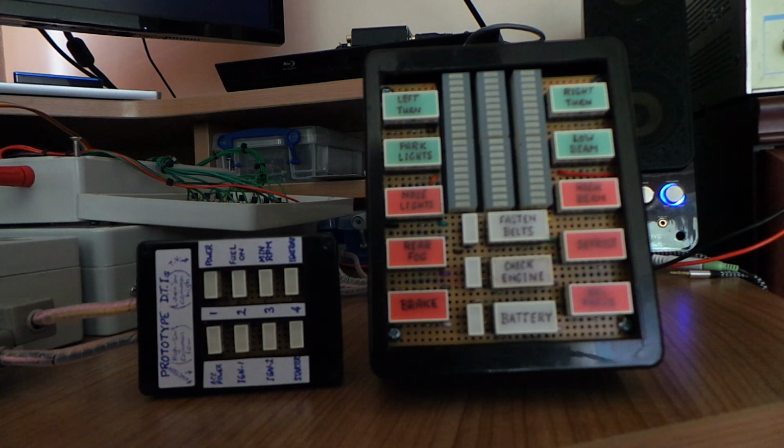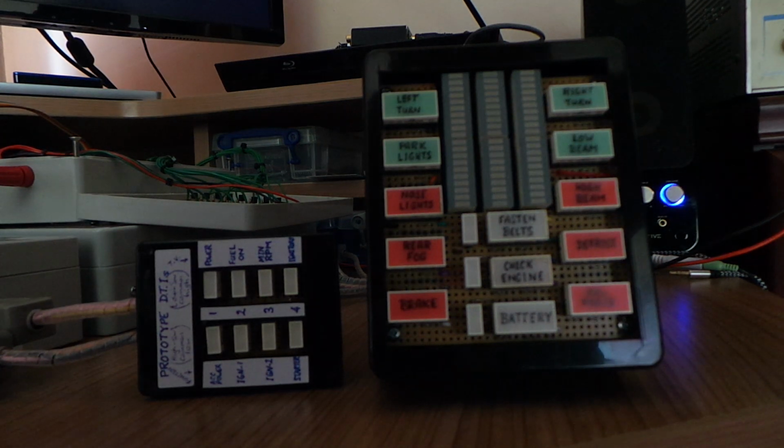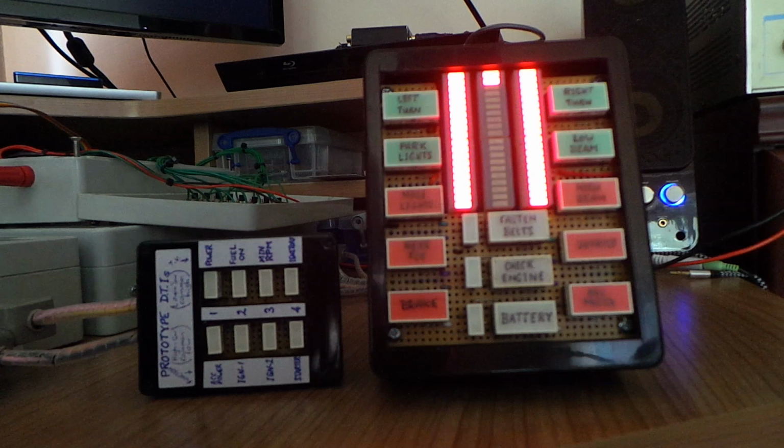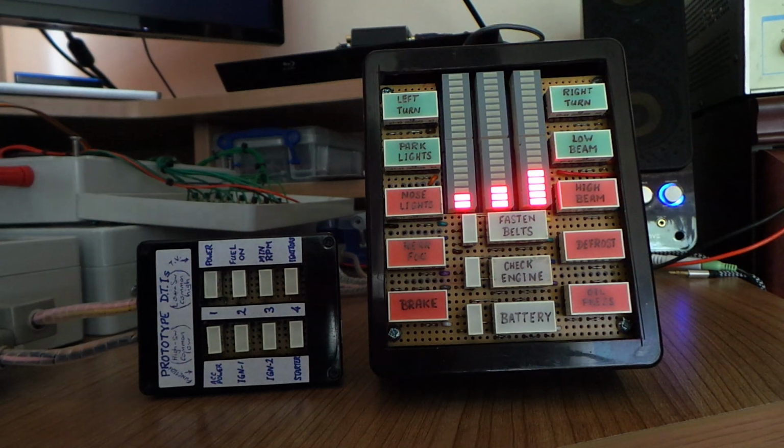Again, we'll go through the menu, so let's power up with the switch number 1 active so that we see the N for normal displayed. We do a short press of push button number 1, and it shows S for show, another short press, O for output test, another short press, I for input test, and then a short press of push button number 2 to go into input test mode.